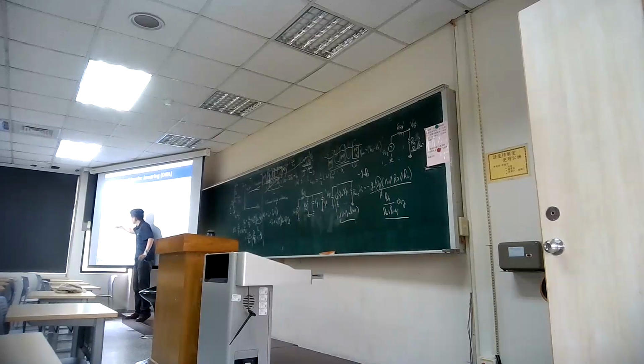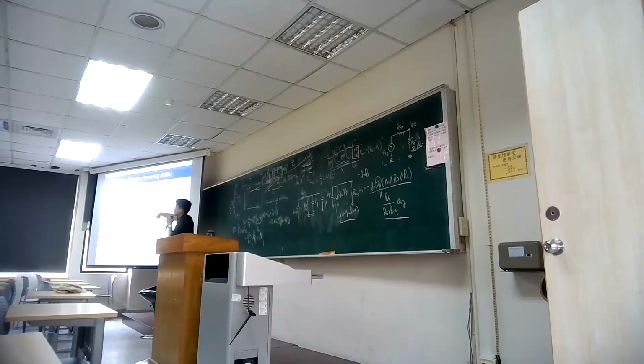So you can consider that initially we have a certain barrier. Here is the N-type semiconductor, P-type semiconductor, and N-type semiconductor. The baseline is without the drain voltage. Okay. So initially we do not have any current flowing through, even if you slightly increase the drain voltage. But here is the really long channel, so you increase the drain voltage. You can see even when we increase the drain voltage, there's a boundary at both the source and drain side. So there's no current.